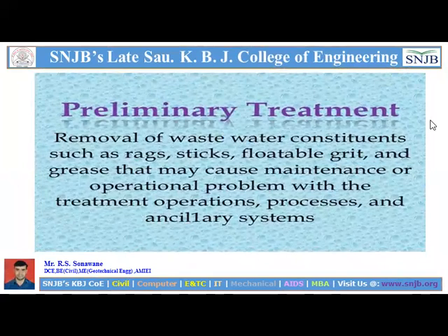So in a preliminary treatment, removal of wastewater constituents such as rags, sticks, floatables, grit, and grease that may cause maintenance or operational problems with the treatment operations, processes and ancillary systems.